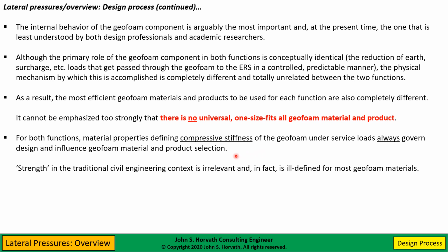Certainly when you test EPS geofoam materials in compression, you do not get a quote-unquote failure. You don't get a material rupture in the conventional, traditional way of engineering material failures. You simply, in very simplistic, colloquial terms, squeeze the air out of the geofoam and it goes back to being solid polystyrene. It simply doesn't rupture in a traditional sense. So strength is irrelevant.